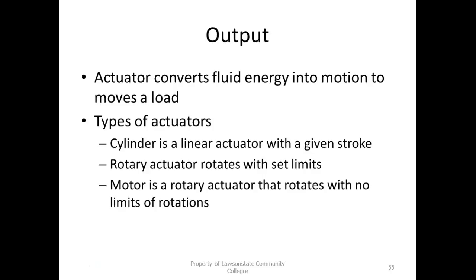What's it say? Rotary actuator. Well, they move in an arc. They don't necessarily move in a circle. A rotary actuator moves in an arc. But a rotary actuator has a limited, what we call stroke. Stroke is another term, the distance the actuator can move.